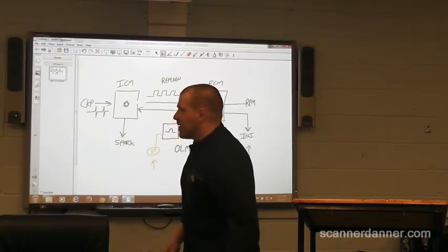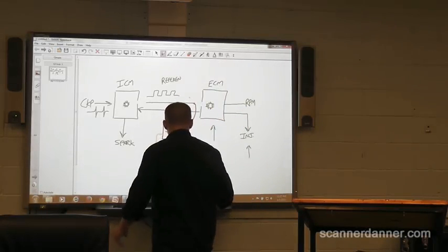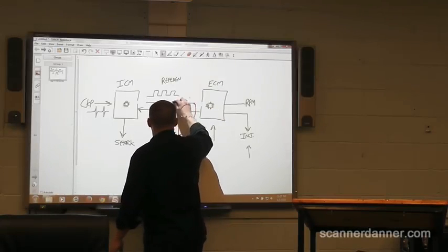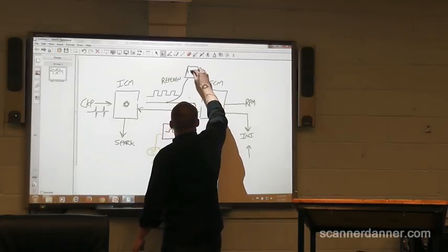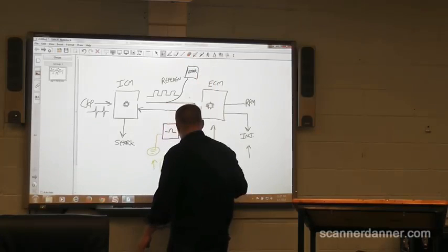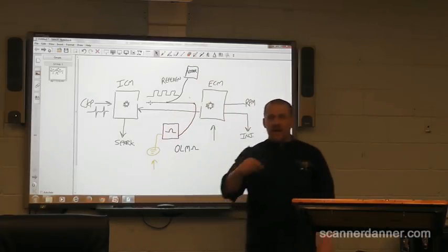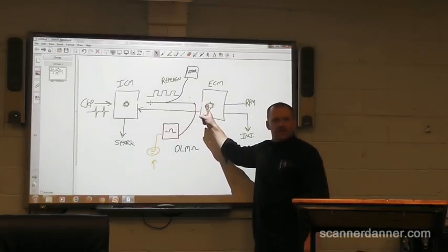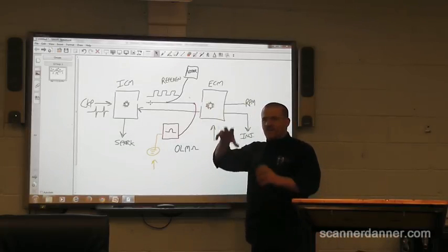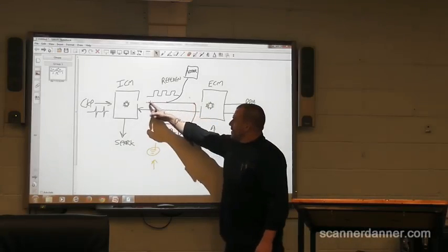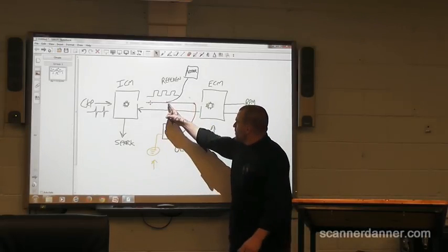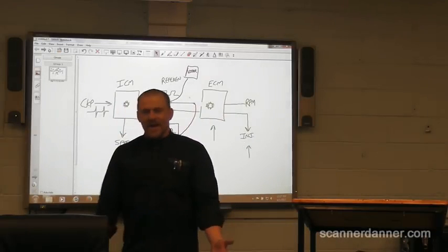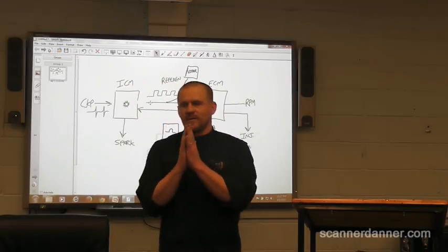Here's what we have. This car has a Viper alarm system wired into it that I did not know was there, and the owner did not know was there. It was a work van, and I found that alarm system in the process of disconnecting the computer to do my short to ground test. I'm following the harness and I see this purple white wire, which is my reference wire, and I see this splice going into it, and I knew right there where my problem was, right?